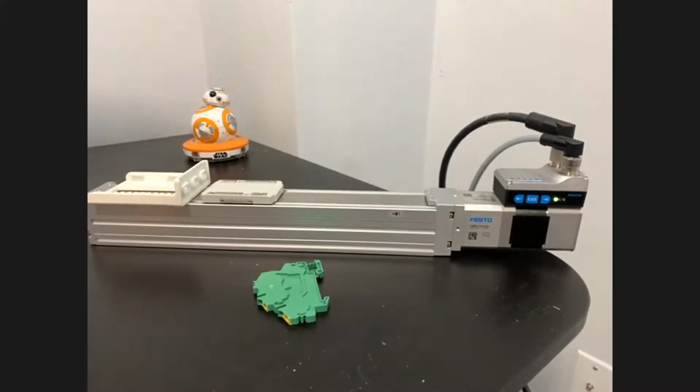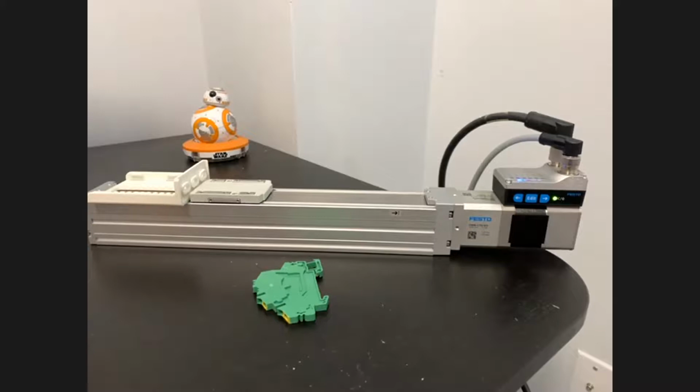Are you able to also pull force values when you're doing the contact? So you could, let's say, collect data not only on the position or the thickness, but also the force? Yeah, you can. For very simple pressing applications, it works great. Say you're inserting a seal into a part, and you want to make sure you see a certain amount of resistance as you're pressing that seal in, and also that it goes to the right position.